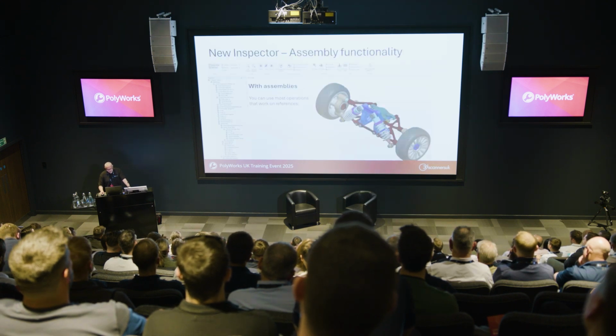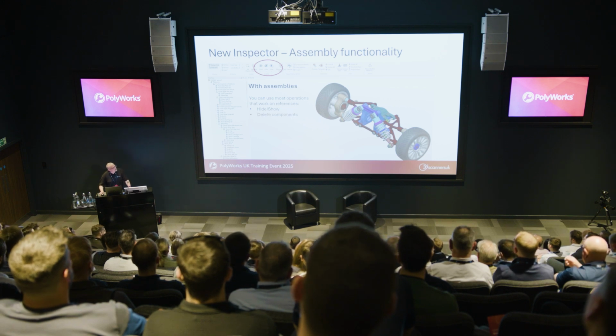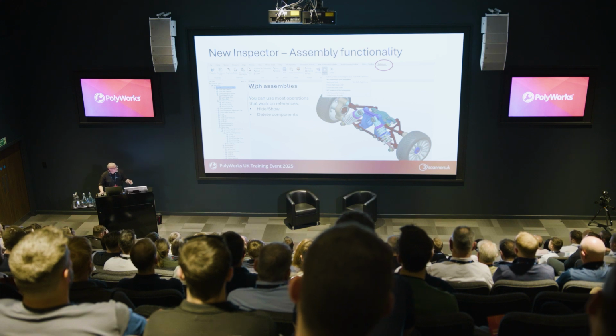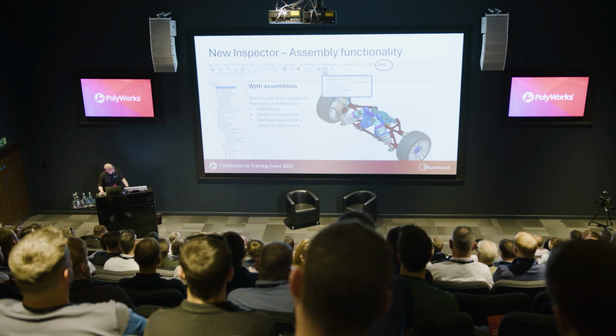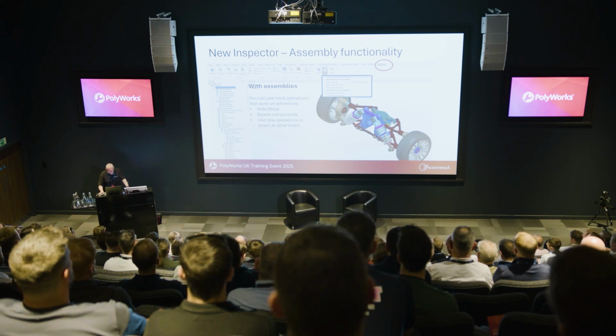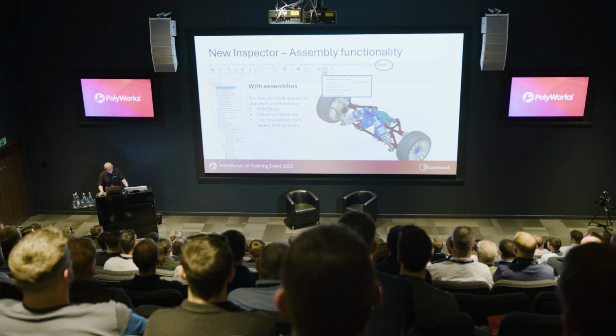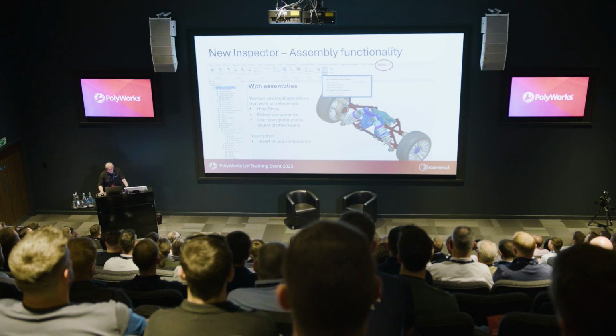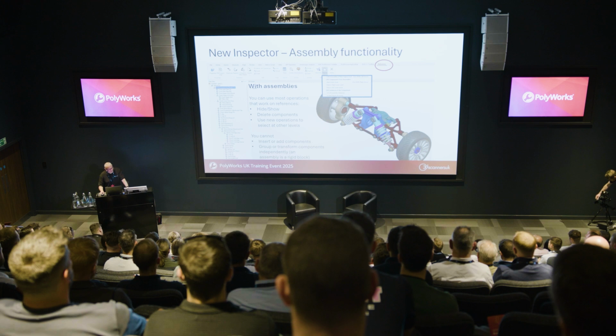With the assemblies, most of the operations that you can use on your standard references work. So we can hide and show. We can delete components from that if we use the contextual reference tab. So we can use any of the operations that we had under the levels that we had for references previously. What we can't do is insert or add extra components. We can't group or transform components independently. The assemblies are a rigid block.